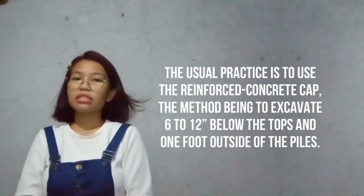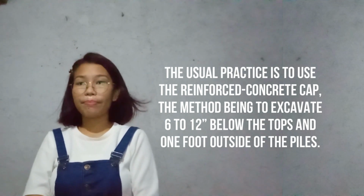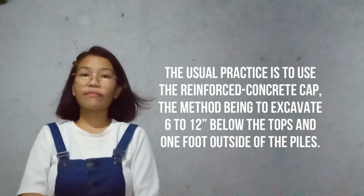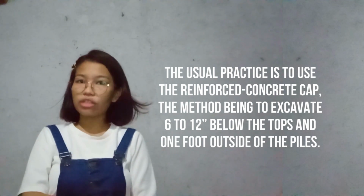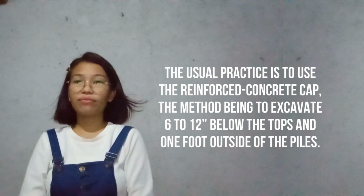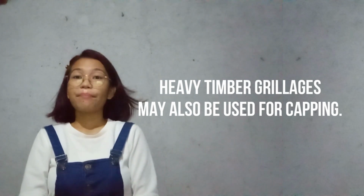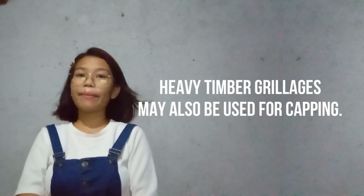The usual practice is to use a reinforced concrete cap. The method is to excavate 6 to 12 inches below the top and 1 foot outside of the piles. Heavy timber grillages may also be used for capping.